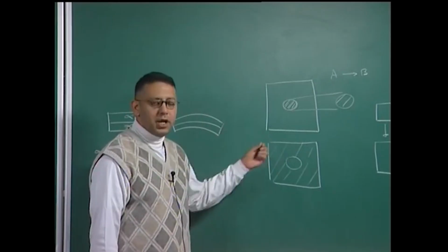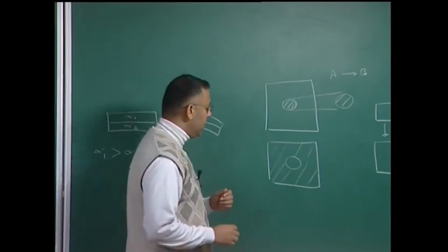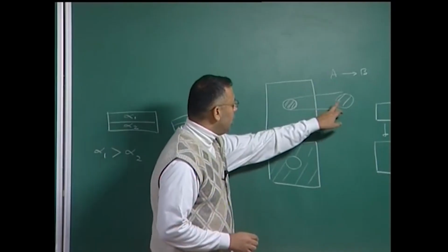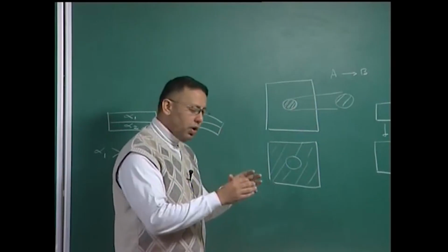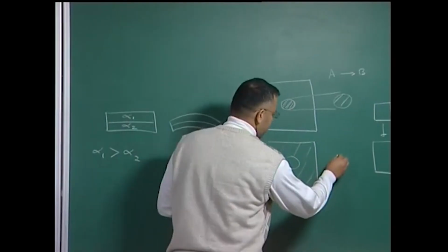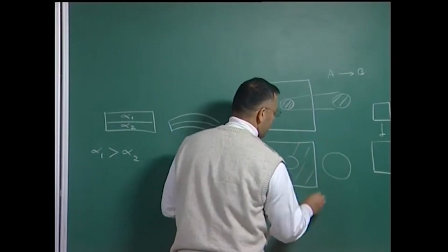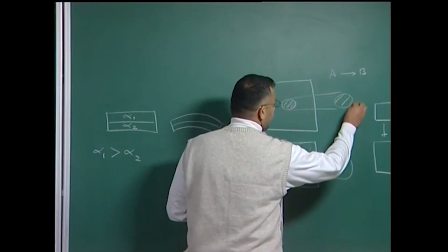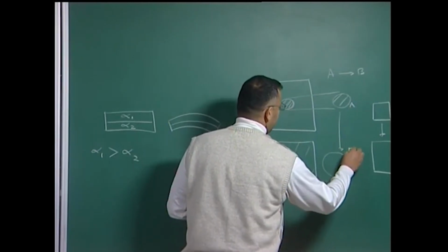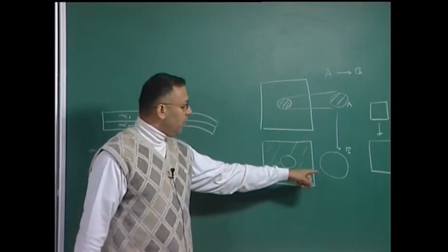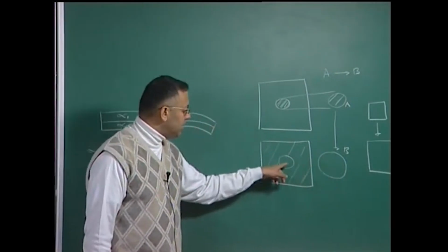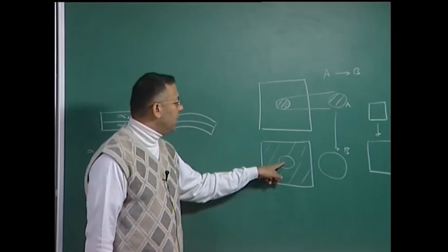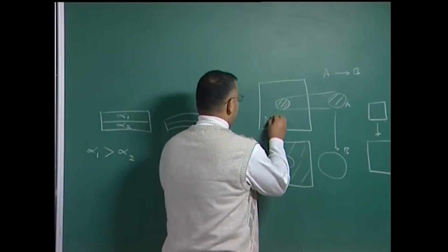For now, for simplicity, I will consider only the dilatational strains. So, the body which was originally occupying a volume V here could be occupying a larger volume or a smaller volume, and therefore, after phase transformation, say for now it occupies a larger volume. So, this is now the phase A which has got transformed into phase B, but this is now a freestanding body which is allowed to freely expand, but in reality this is actually embedded in this other material which is now a matrix material.